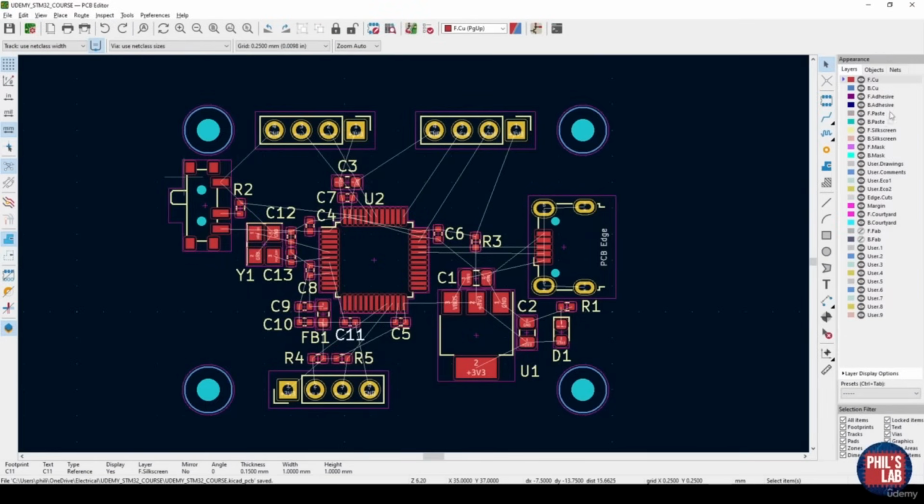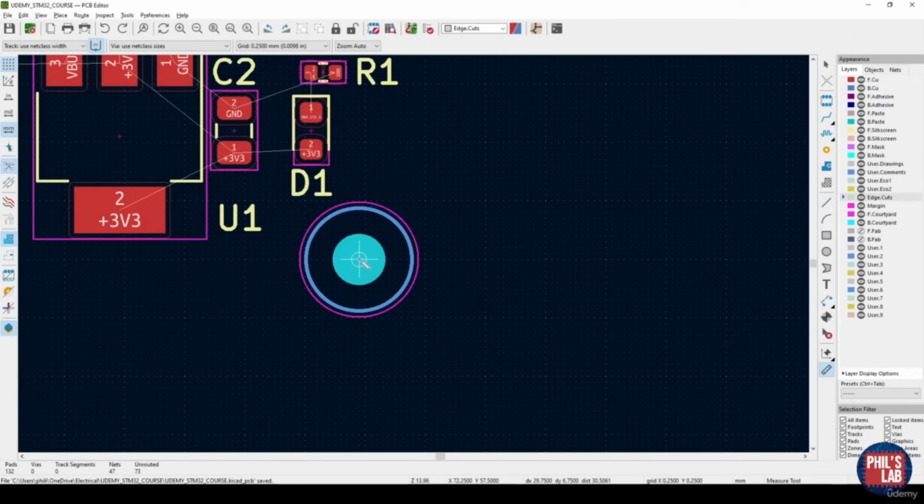And the way we do that is by going to the edge cuts layer over here on the right, clicking next to it, and then using the draw line tool. So I'll try to go out a specific distance away from this mounting hole, let's say maybe 3 millimeters. Remember, we want to give the screw head some sort of space, and this is indicated by this pattern outside here. So 3 millimeters seems to be okay. Let me just draw lines outside.